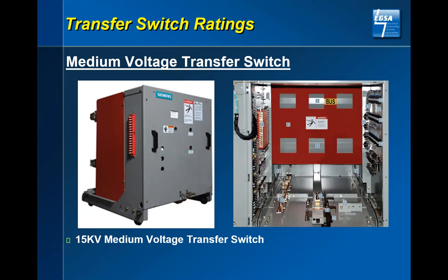Why do I say that so stringently? When you use a medium voltage transfer switch that's using two of these breakers, now you're required to have some type of protective device, an SEL relay or some type of relay, that is going to protect this for overload, short circuit, or that type, and also to tell it when to transfer or such. That's a very keen point.